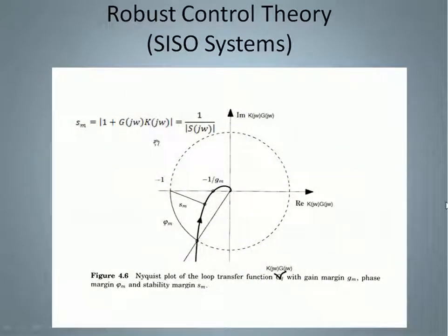In this Nyquist, we assume that the open loop transfer function is a minimum phase system. By noticing that the Nyquist does not go around the point -1 j0, we conclude that the closed loop system is stable. By going around the point -1 j0, I mean this.